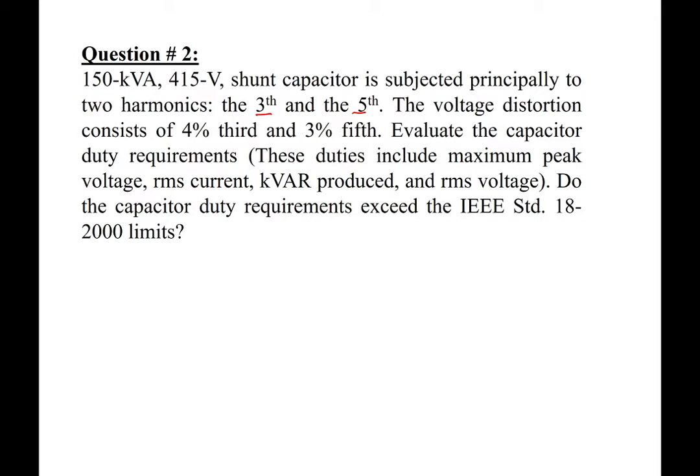So we would like to compare the capacitor requirement with what is specified in the IEEE standard 18-2000 limit, and those are the duties. They include the peak voltage, root mean square current, kilovolt ampere reactive, and root mean square voltage.